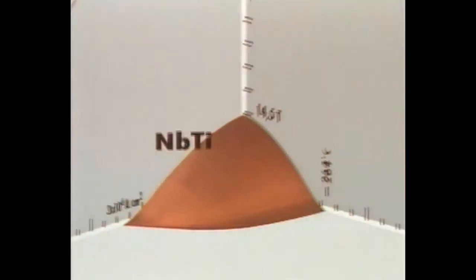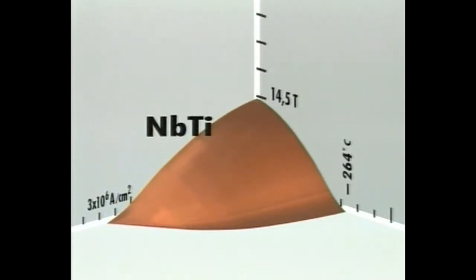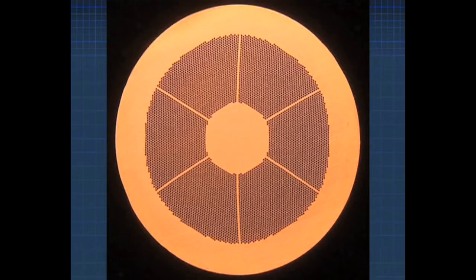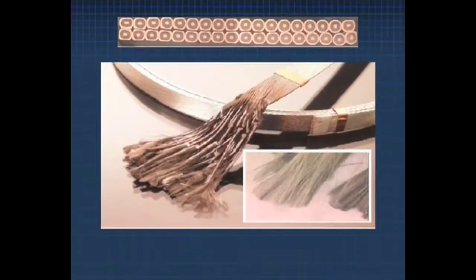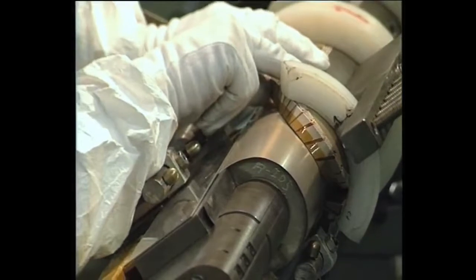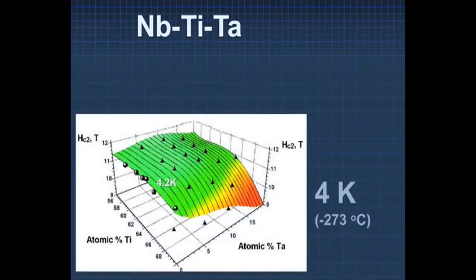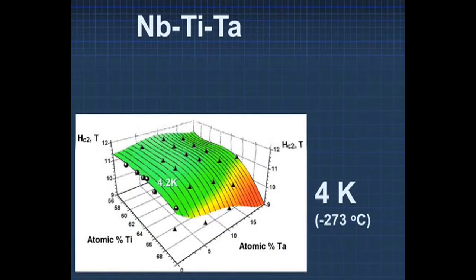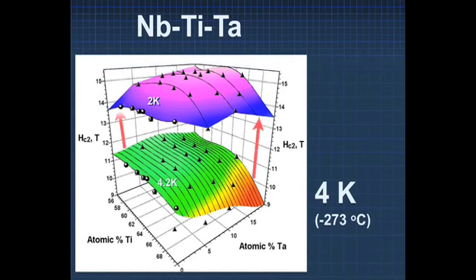The material chosen for the LHC is niobium titanium, which is superconducting at the temperature of liquid helium. It has the indispensable mechanical resistance qualities required to resist the configurations designed by the LHC engineers. Moreover, to improve the performance of the magnet, it's been decided to use helium at -271 degrees Celsius.